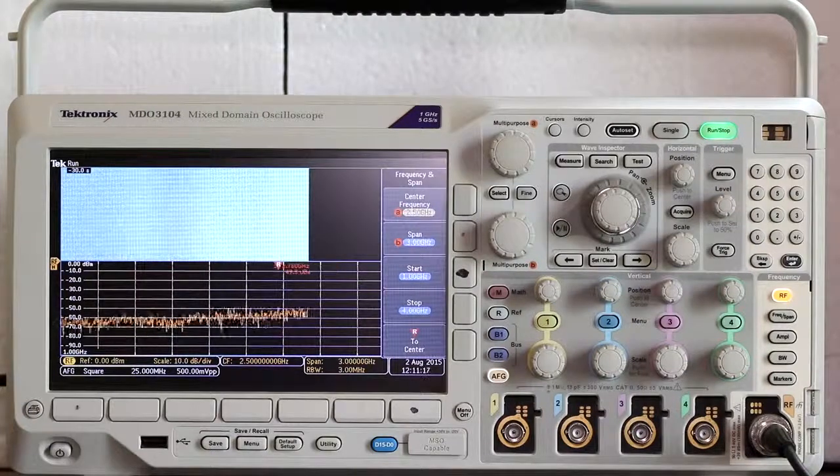In the spectrum analyzer mode, the x-axis is no longer representing time, but instead frequency. Notice that when the square wave is viewed, the greatest power is still in the fundamental, but there is also considerable power in the harmonics. This is in contrast to the sine wave, where all the power is in the fundamental.